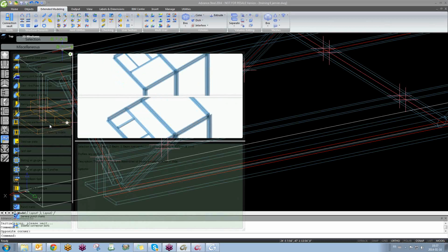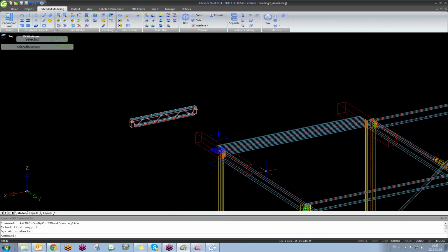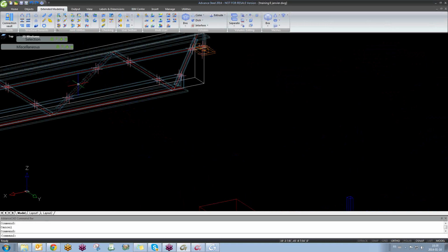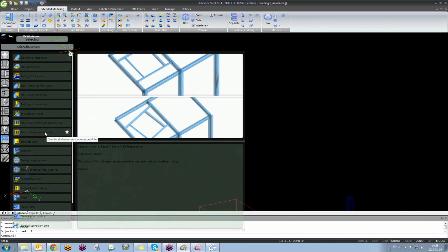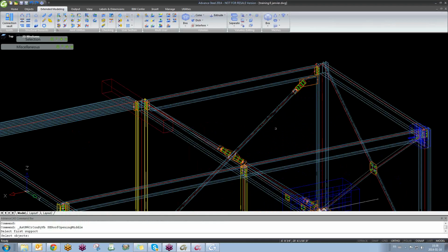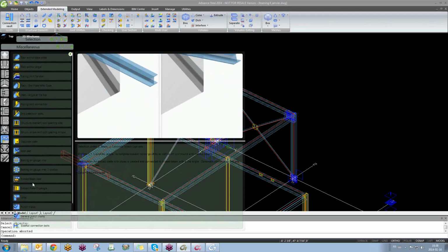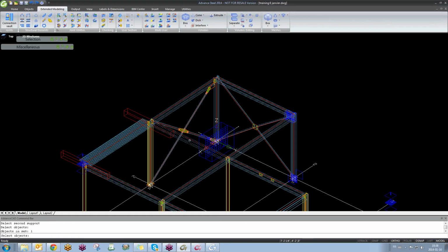Structured element roof opening side. When you click here, it's just to give you a taste and an idea of what the thing looks like. So let me delete this first. Here I have the structured element roof opening. You have to select your two joists. Select the first one, enter. Select the second one, enter. Additional support.